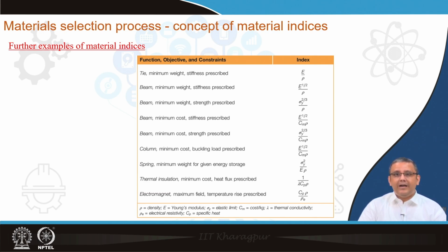the material. So, we can also bring cost as a parameter in the denominator, and that will again give a new material index, sigma_y squared divided by E multiplied by rho multiplied by C, and this way, as a materials engineer, for material selection purposes one can design or create several new material indices. Many such material indices for some standard applications have been shown in the book of Mike Ashby on material selection for mechanical design.